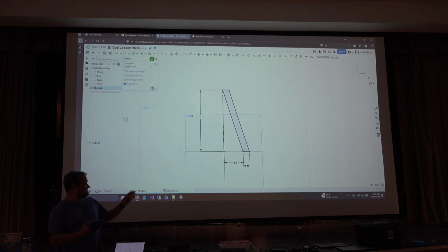All right, we're working in radius, not diameter. So right now we're 1.5 inches from the center point to the outside part, which means our radius is 1.5 inches, technically 2 inches to the outside part because we have 1/2 inch part. So when we revolve this, when we make it the full part, the full thing is going to be 4 inches in diameter because it's 2 inches in radius.